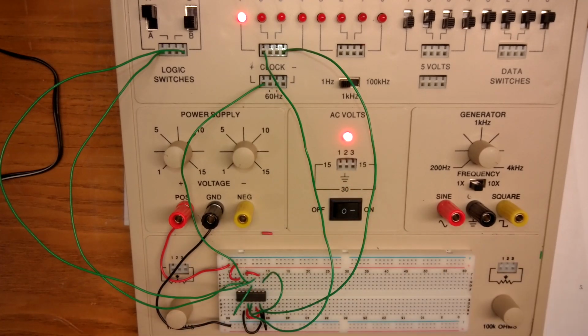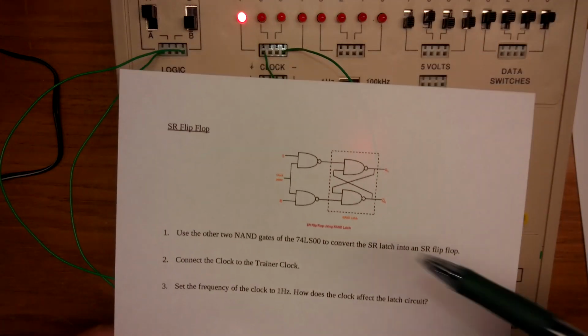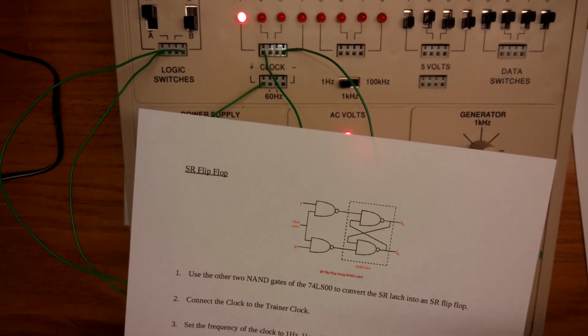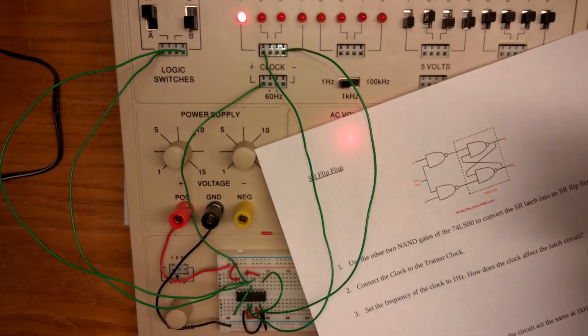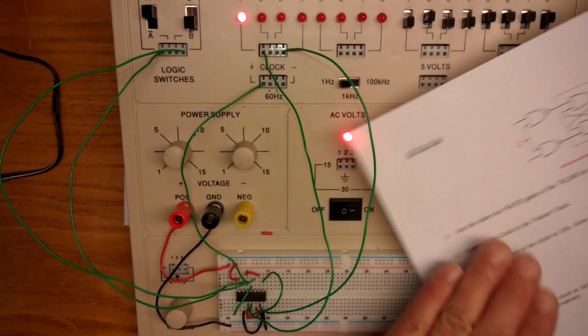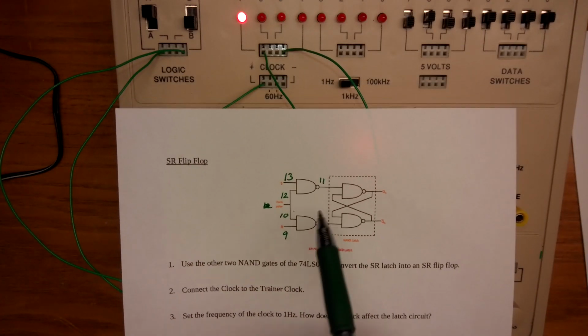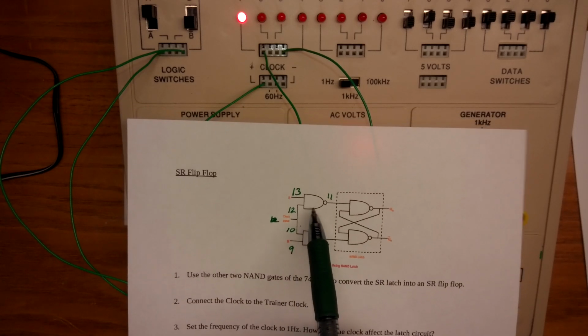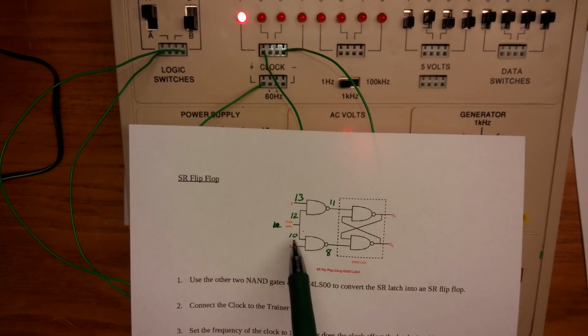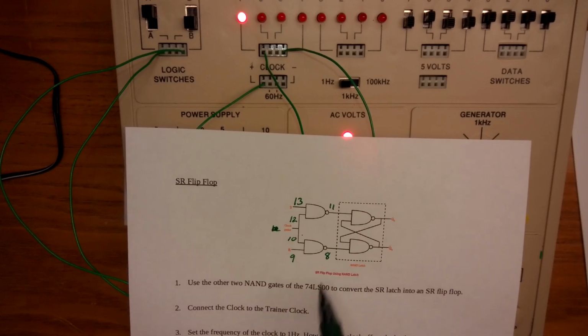Now, one of the things you can do with this, I didn't do it here, but you could go through and list these. Like, power is 14, so I might say, hey, this is 13, this is 12, this is 11. I'll show you here. So I might go over and just hold them up next to my pinout and say, hey, 12 and 13 are inputs to this top left NAND gate, output's 11. The one on the top, 9 and 10 are inputs, output is 8. So write them on there.